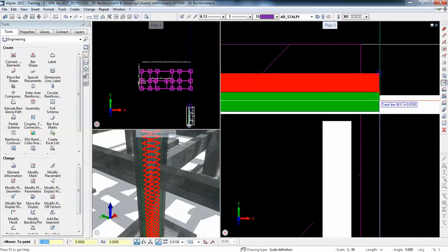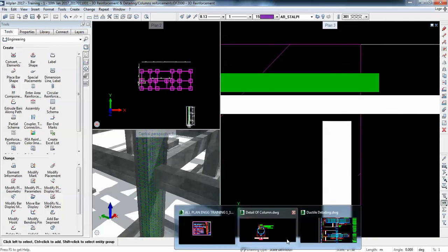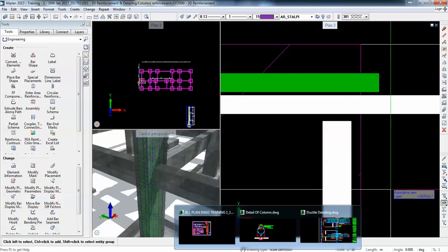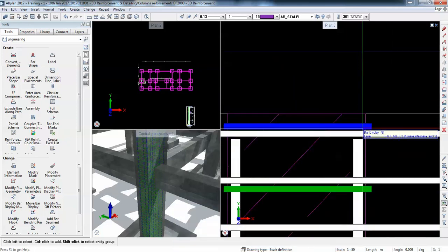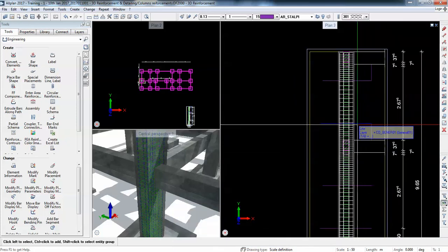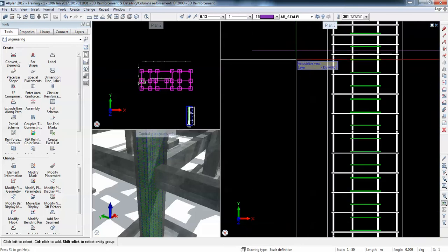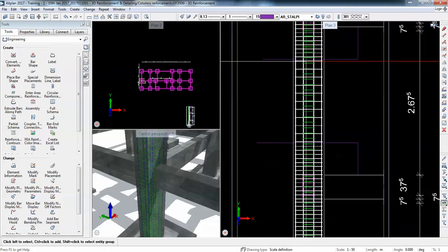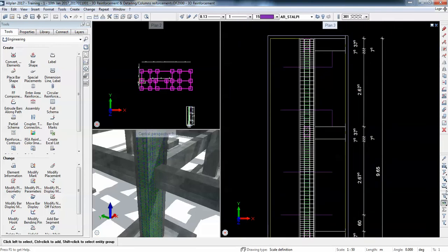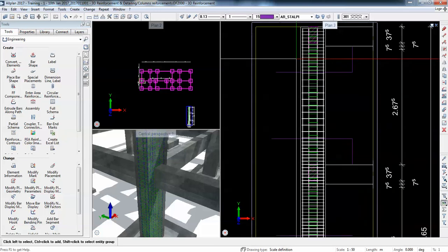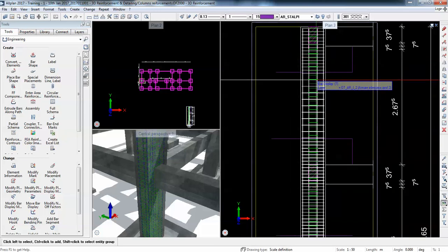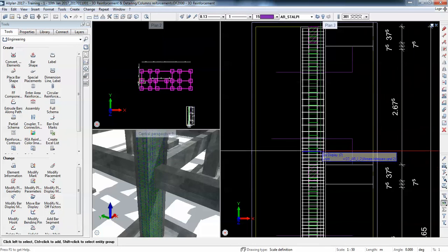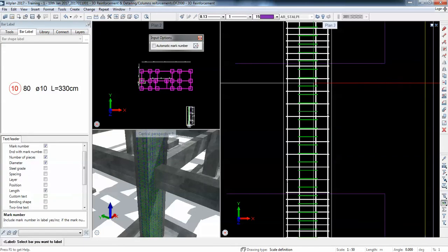But if I want a simplified drawing where only one line is for the package of the stirrups, I'll just have to hide them by placing in between. And of course, I have to solve the other issues in order to make sure I don't come in contact with the other stirrups when I'm doing now the selection. I can use a filter. So I will identify the mark.